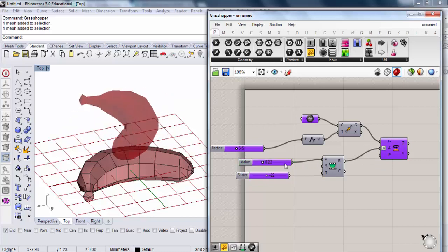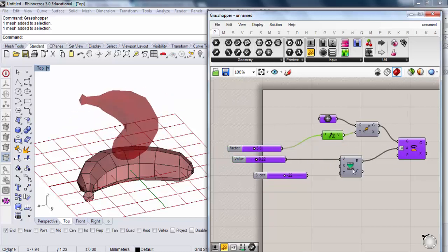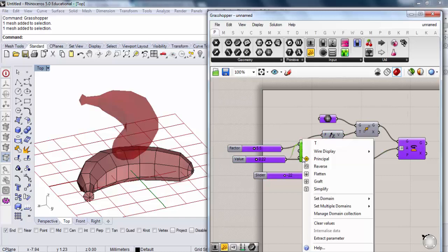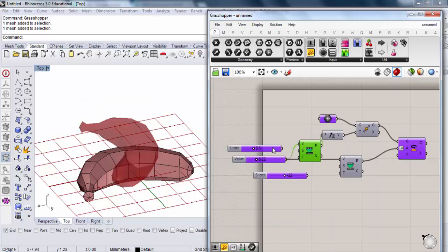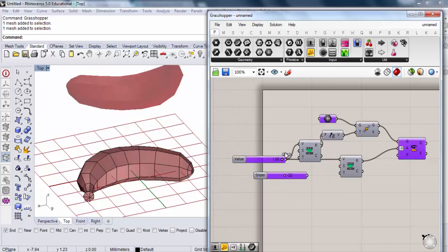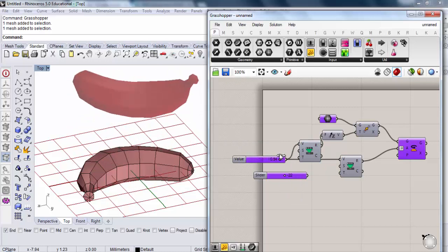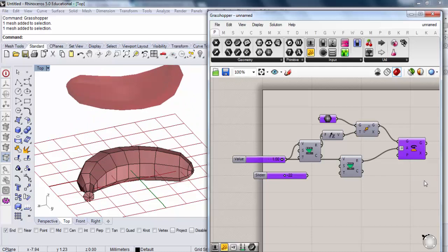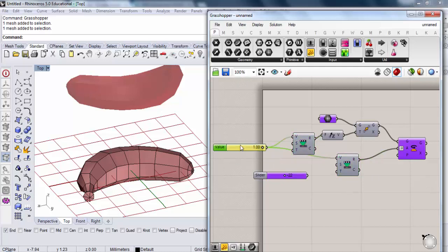There, that just rotates it, and then I can create another mapping thing so that my domain is just, say, 0 to 10. Put it in there, and then I can do both. That's parametric now. Okay, so one slider controlling two values. That's the basic concept of Grasshopper, and there's infinite applications for this.